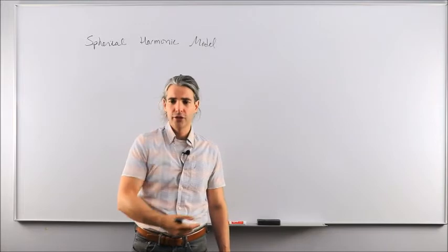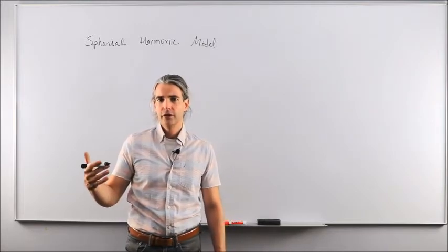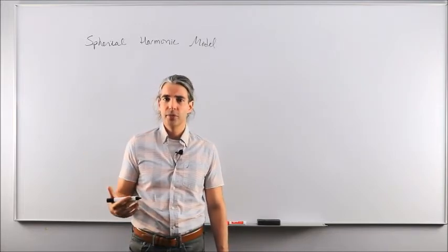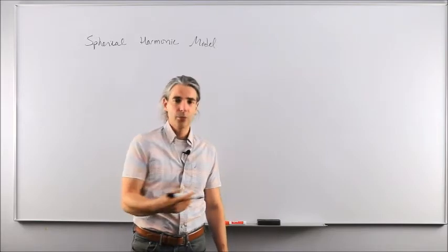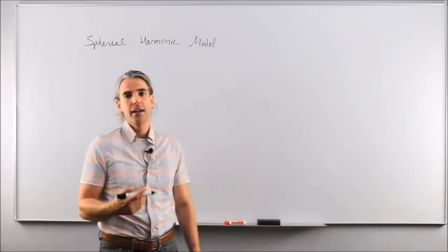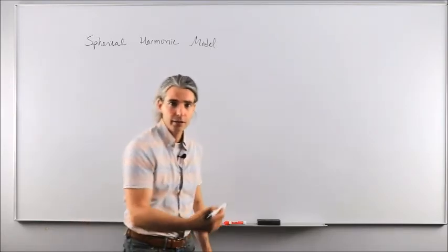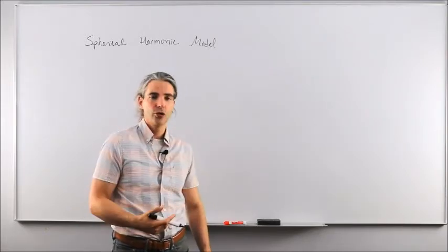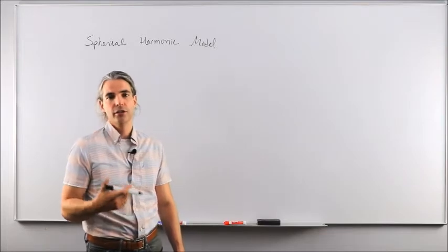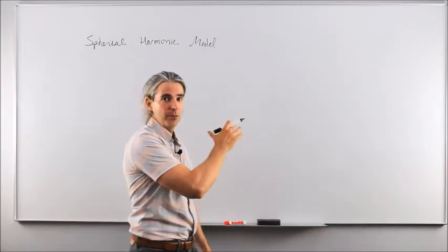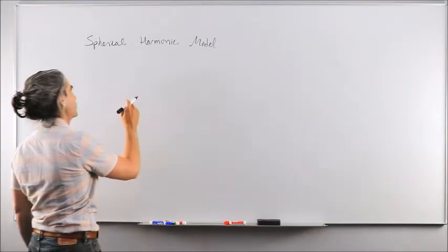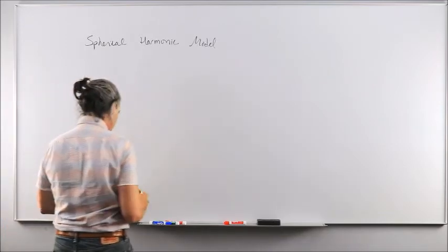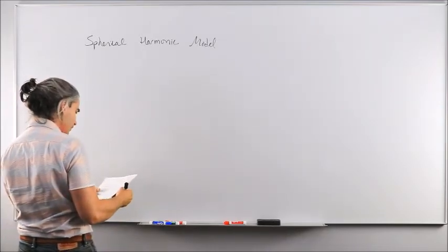And then we had looked at the first degree and first order of that double summation equation to end up with the J2 effect at the end of the day. And then taking the gradient of this potential field, we had then obtained the perturbing acceleration due to J2. Well, here is going to be the exact same thing, but in terms not of potential field, but in terms of magnetic field.